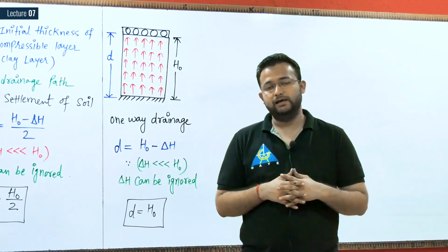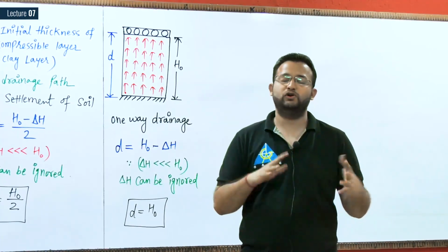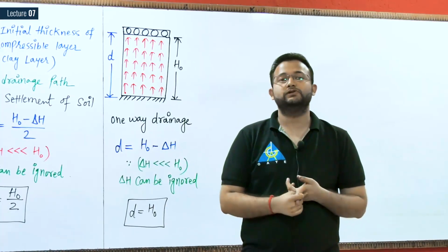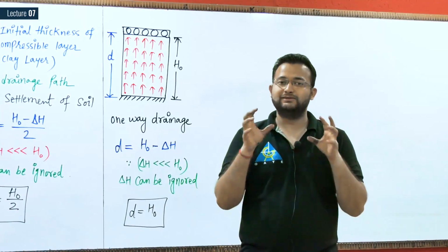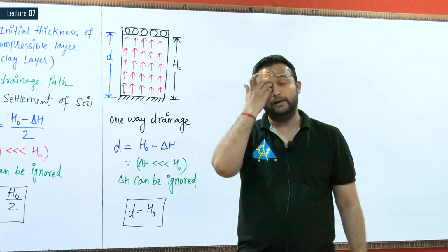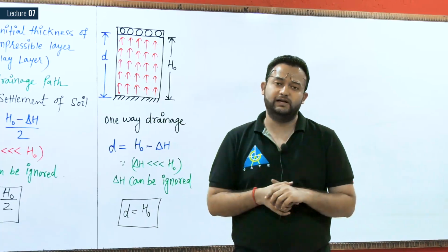Now after filling the rings with the soil, we keep the porous plate according to one-way or two-way drainage. Now we apply the load. One thing you should notice, that the soil which has been filled in the ring should be fully saturated.